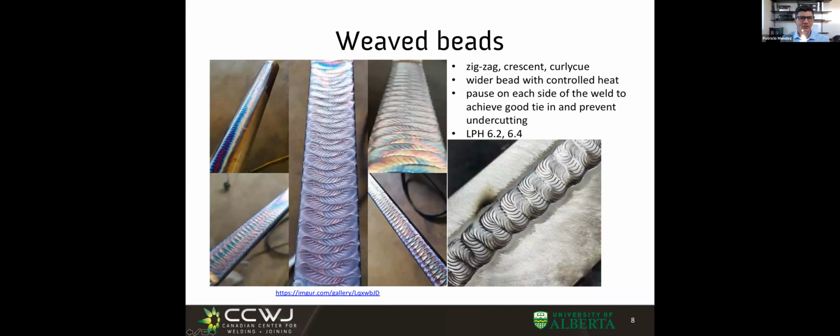And these weaves, I don't think those are everyday weaves. They look more like artistic weaves, but I think they are so awesome that I wanted to share these with you, right? You can totally tell how they were weaving here, right? And in this case, this finish is called a stack of dimes. And this is an aluminum weld. They don't tell me, but this much I know. I can tell because of the cleaning action around it. And this is with a pulsed program. And every time the torch pulses, it creates a weld pool that looks like this stack of dimes here, right?